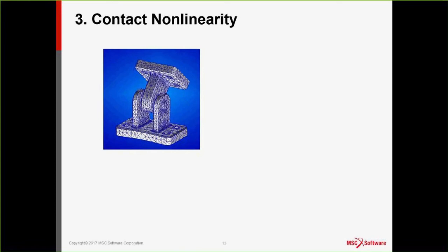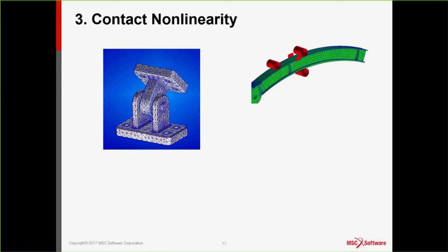We see a lot of our users coming into nonlinear analysis. First problem they run is contact. It just is very common in assemblies. This is a simple example I'm animating here. It's very exaggerated, the deformation, but this is actually a close fit lug, pin, and clevis assembly. So the deformation is actually really small. But you can see here the only load path is contact. There's nothing else. So we have to simulate contact between these contact bodies.